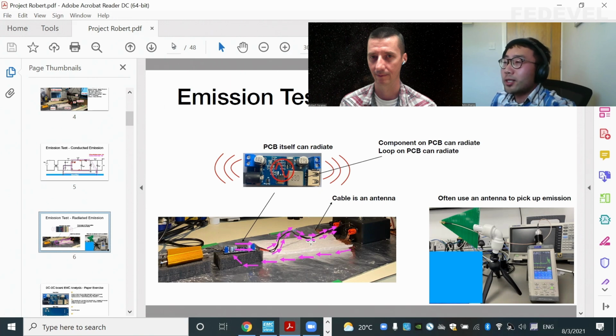Most of the time, you start the winding process at pin 1 and wind around it, and your end winding is on the outside. So all the other layers shield your pin 1, the starting point. That pin 1 is well shielded by the outer layer of the winding.